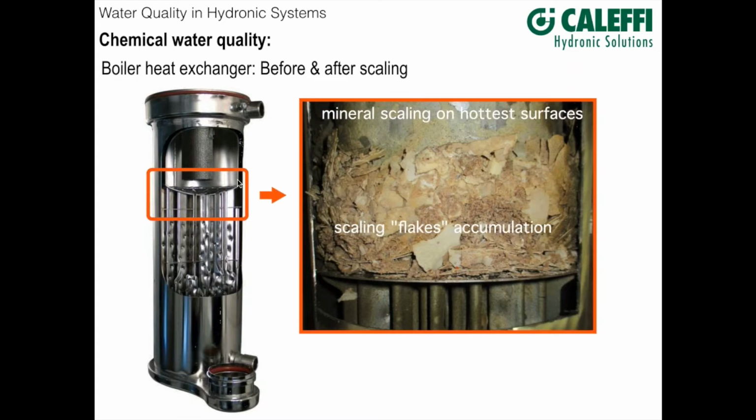And with the expansion and contraction of that upper portion of that heat exchanger, over time these flakes will break off and settle down, and again you can see that they are going to inhibit water flow through that heat exchanger. Some of that material is inevitably going to get down on the inside of that heat exchanger and cause fouling. And I'll show you a graph in a minute that has a profound effect on the efficiency and the fuel use of that boiler.